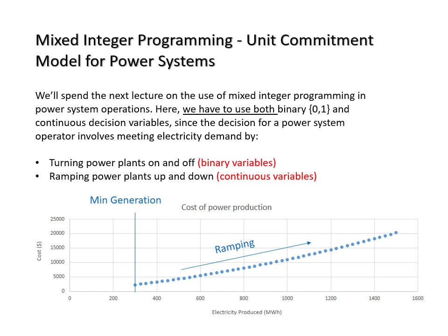And there's a special class of mixed integer linear programs called unit commitment models that help utilities do this, and everyone uses this approach. Academics use it, researchers, industry, etc. And you can make these models more or less sophisticated depending on what your objectives are. But it's a really good class of models to sort of understand.